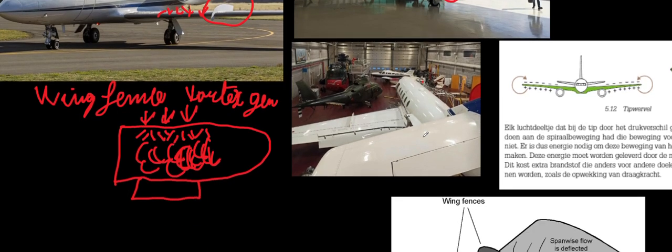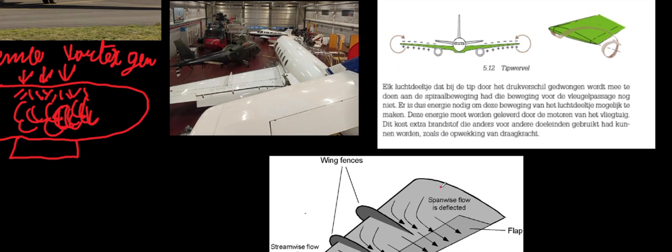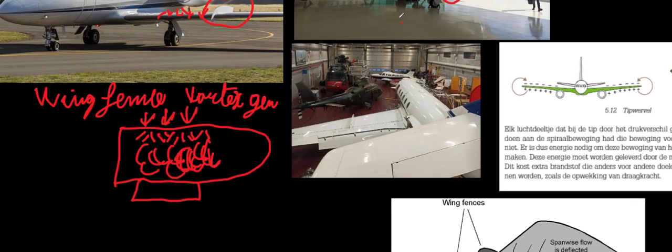Now, first of all, I have to explain wingtip vortices. So what happens on the wing is that you have spanwise flow and also streamwise flow. Now, the streamwise flow is what you've probably already learned of, and it's what we're manipulating here when using these vortex generators.